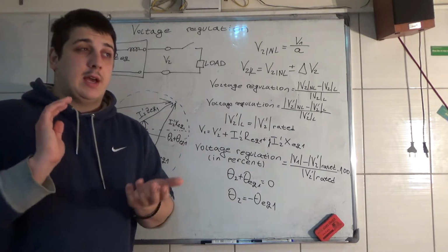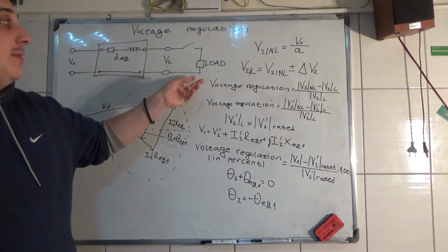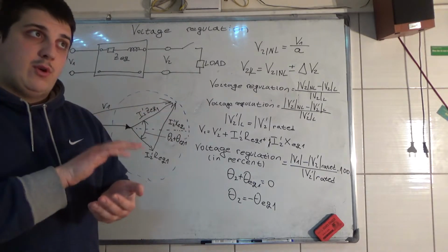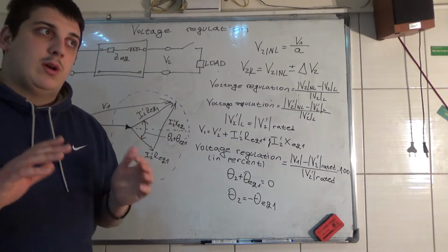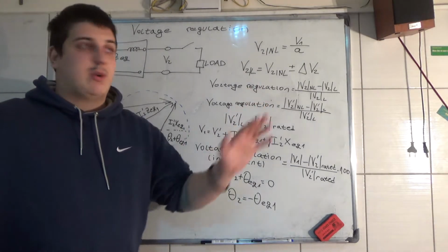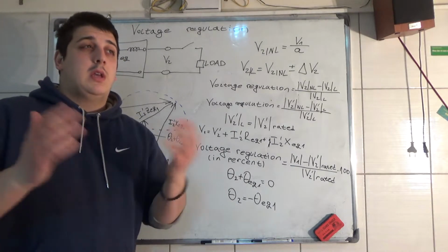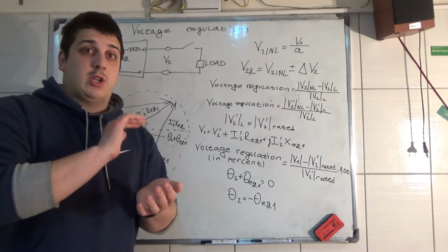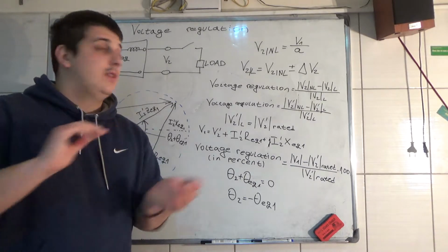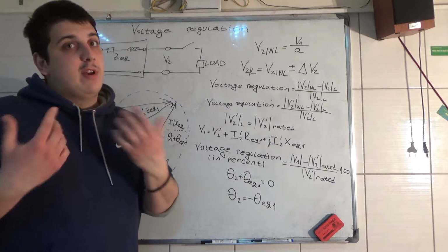They sometimes connect a capacitive load, sometimes a more inductive load. If you have a resistive load, that doesn't make much trouble, but capacitive and inductive loads can change this terminal voltage V2 very much.